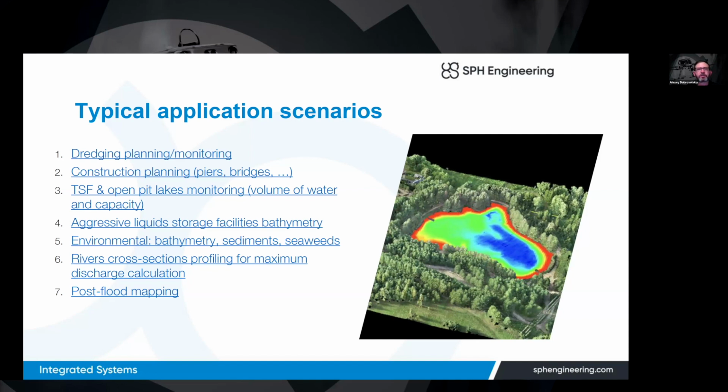The most interesting scenario I saw was the bathymetry of open air storage with dissolved acidic solution. Bathymetry using a drone, in many such cases, is the only possible scenario, because you cannot use the old-fashioned way, I mean a guy with a measurement pole, and also remotely operated vehicles or robot boats may not have enough lifetime in such liquids.